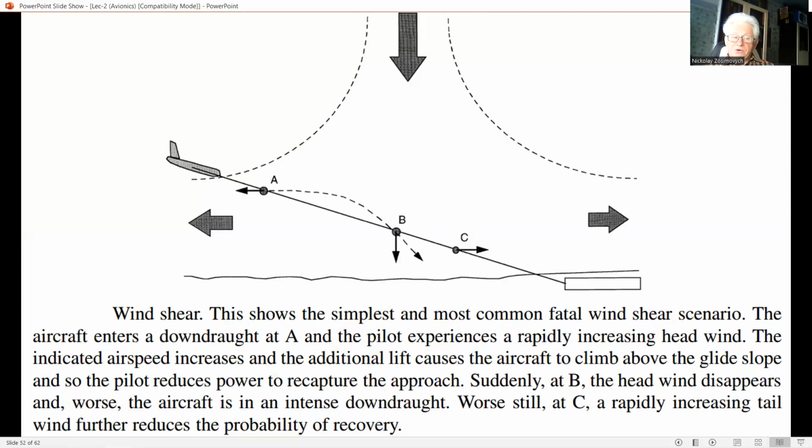As explained a bit earlier, the HUD displays a video image of the real world ahead of the aircraft derived from a millimetric wavelength radar sensor and a FLIR sensor installed in the aircraft, together with the overlaid primary flight information and flight path parameters. And fourth, the use of the HUD for displaying ground taxiway guidance is being actively investigated and is considered a likely extension to the HUD's role. Ground taxiway guidance could be provided by differential GPS.